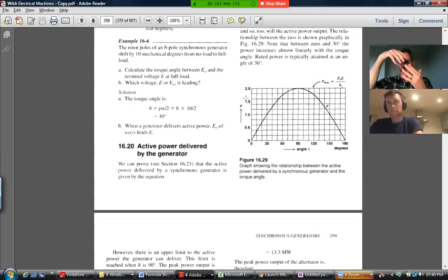Yes, that thing could be slightly ahead or slightly behind, depending if it's a motor or a generator, but it still continues to spin at exactly synchronous frequency. It's just slightly out of phase. So the speed is completely fixed. So power equals torque times omega. So omega is fixed. So basically more torque means more power. And you get more torque essentially by increasing, well, more torque makes that so-called torque angle increase. And this here is in electrical degrees, not mechanical degrees. You always want to get in electrical degrees to draw it on the phasor diagrams.